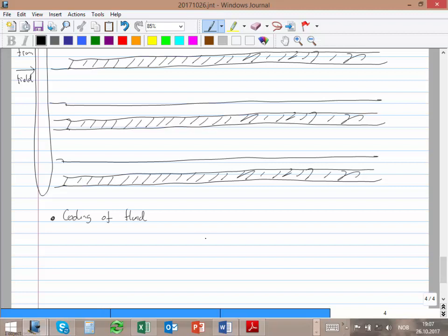When I use a bigger pipe, if I look at the pipe cross section, I have more area exposed. Let's say you have here the temperature of the fluid, and the temperature of the ambient. If I have a small pipe, the area that is exposed is very small, so you lose temperature very, very slowly along the pipe.